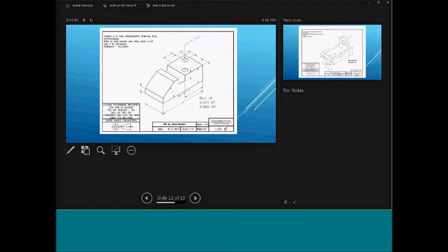It's kind of up to them to figure out where to create these features. For instance, the holes are the easiest to create on the top view, and then project them down as hidden lines to the front view and the side view. So I'm trying to give them some techniques here. It's not just about creating each view independently. It's about being able to transfer things and use the geometry that you have on the screen wisely, and trying to make this as easy as we possibly can.